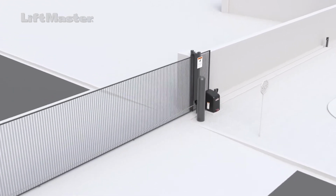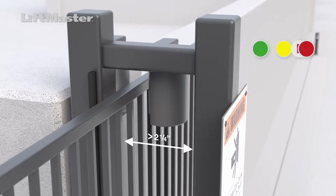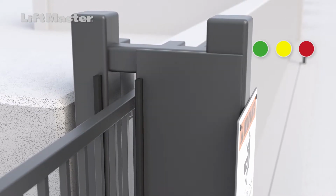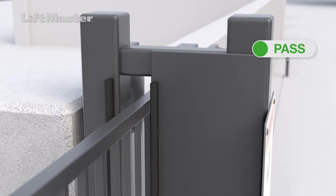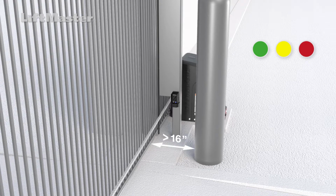Sliding gates should never have a gap exceeding 2 1/4 inches from fence or gate support post. If a gap exceeding 2 1/4 inches exists, a panel must be added to reduce the gap. In addition, entrapment protection is required to protect any gap in this draw-in area. Any stationary objects that are more than 16 inches away from the gate frame do not require any corrective action.